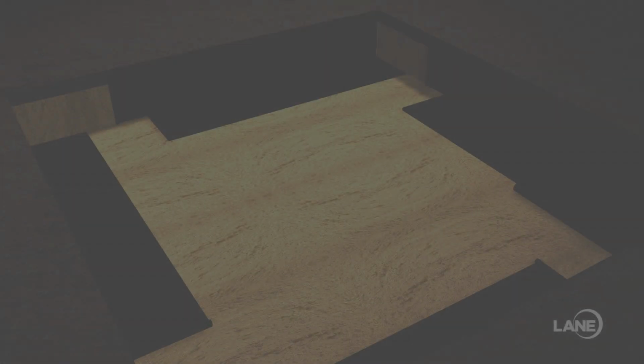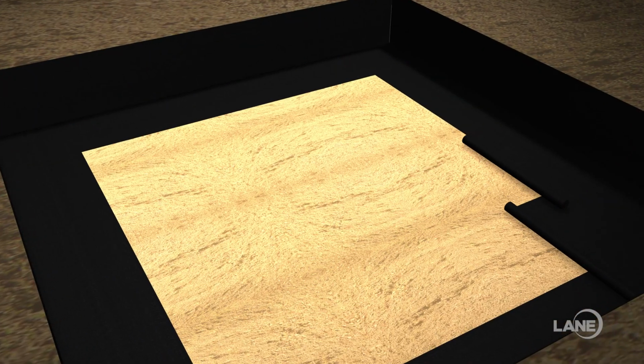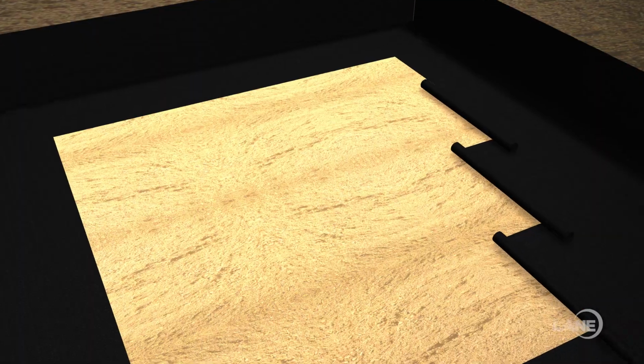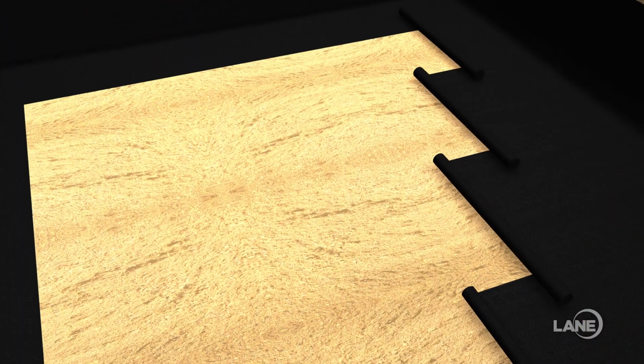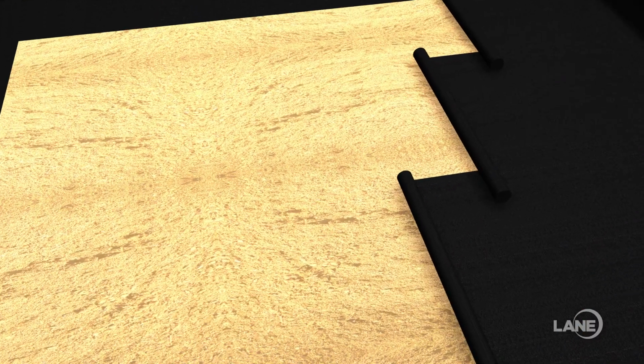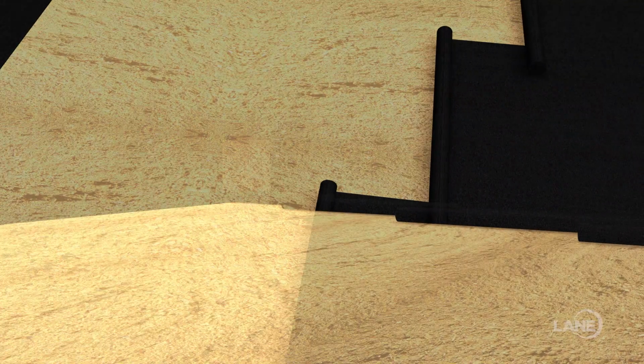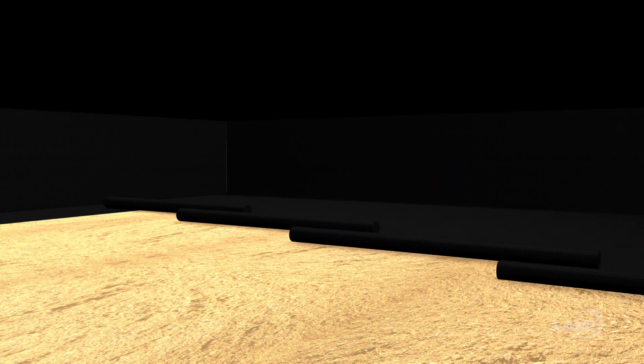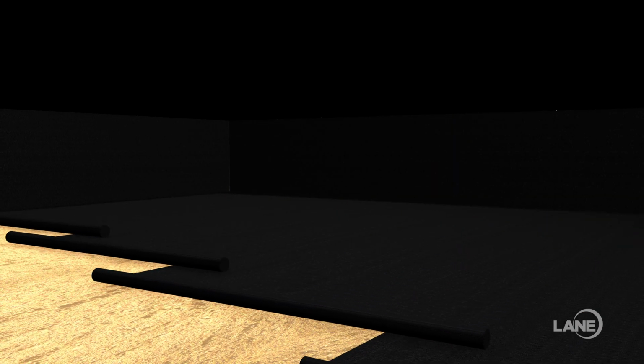A 6-ounce non-woven geotextile is used to cover the bottom and sides of the excavation to form a barrier between the native soils and the chamber system storage envelope. The geotextile should be rolled in the direction of the chamber rows while maintaining a 24-inch overlap with adjacent layers.